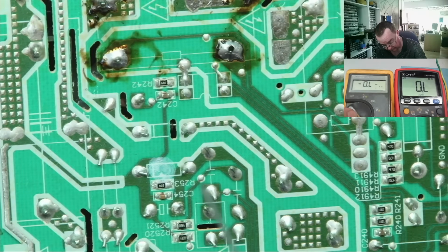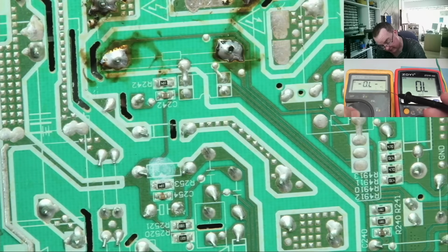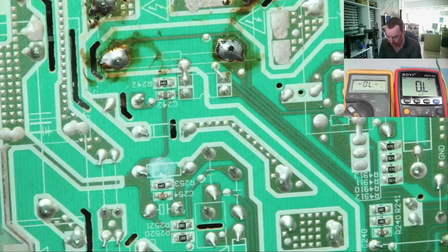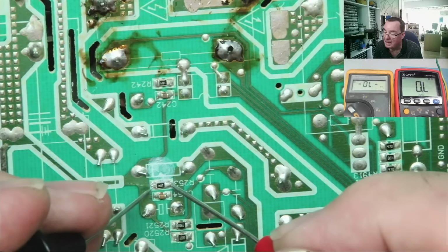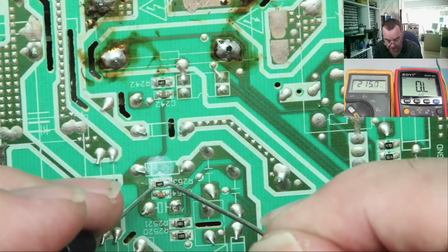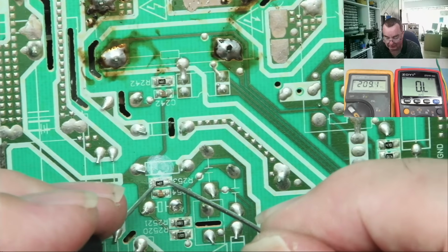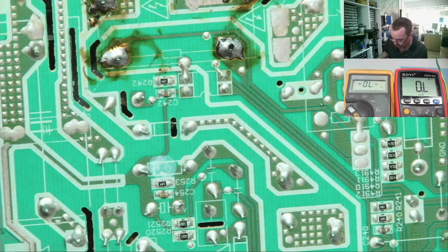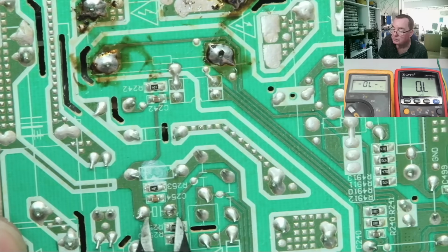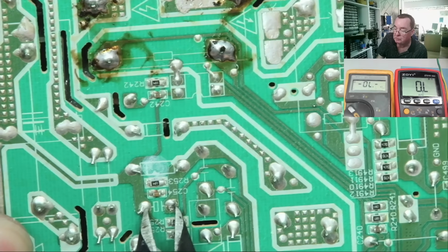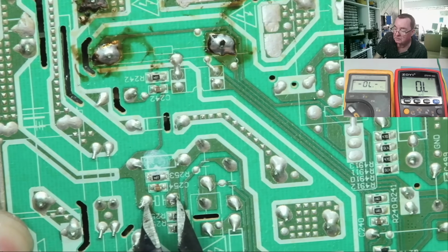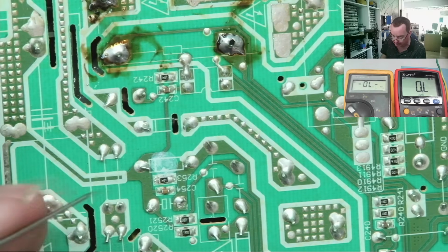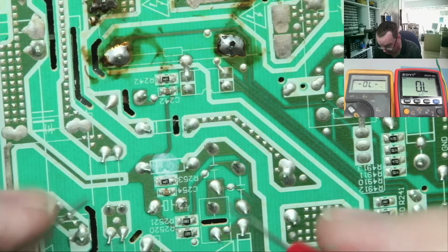So if I go to kiloohms, tens of kiloohms, hundreds of kiloohms, and measure again, you'll see it's reading higher and coming downwards. Now if I just short out the capacitor, which won't have a lot of voltage in it, it's just a very small voltage from my multimeter, and we go again on manual ranging mode.